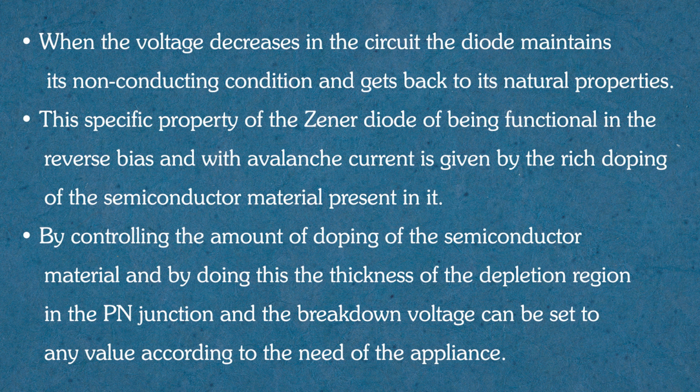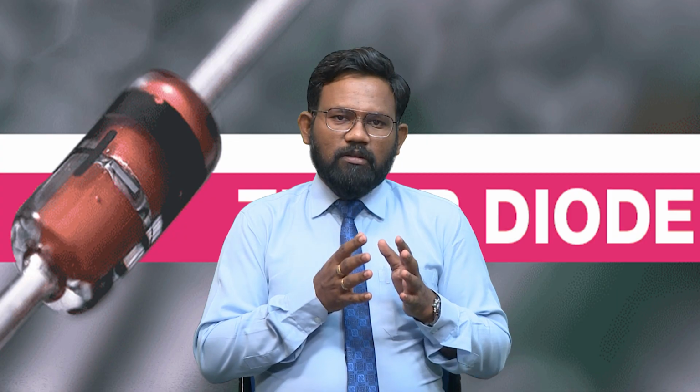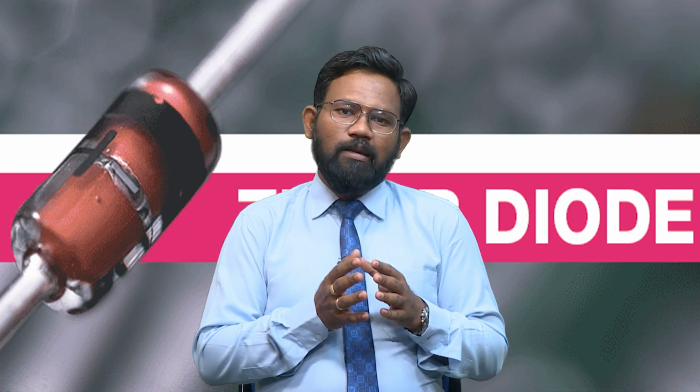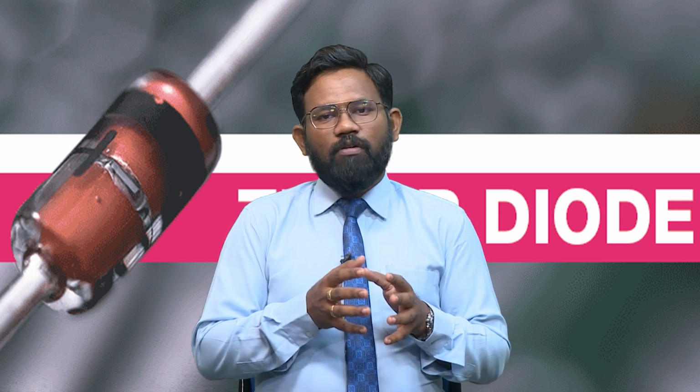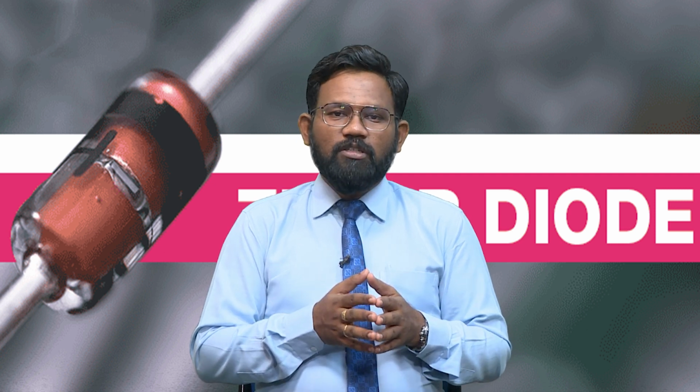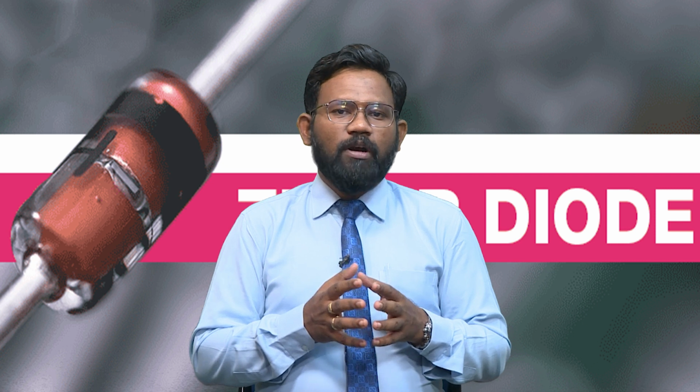This specific property of the Zener diode, of being functional in reverse bias with avalanche current, is given by the rich doping of the semiconductor material present in it. By controlling the amount of doping of the semiconductor material, the thickness of the depletion region in the PN junction and the breakdown voltage can be set to any value according to the need of the appliance. This means that the thickness of the depletion region depends upon the amount of doping, and this thickness decides the amount of breakdown voltage.